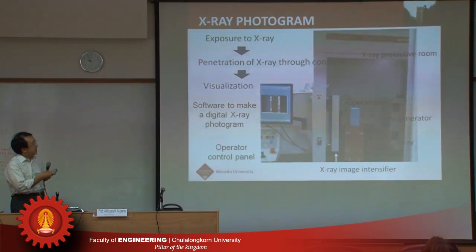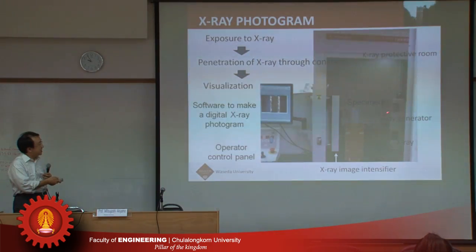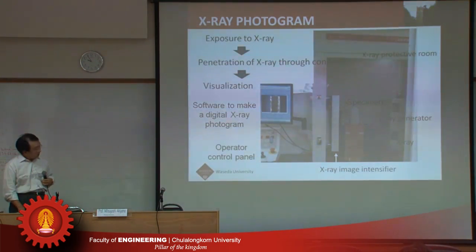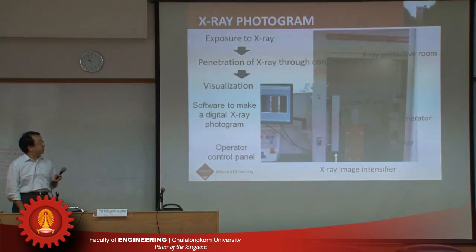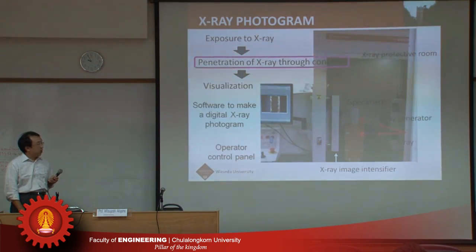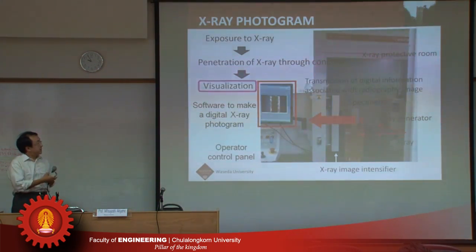The specimen can be rotated like this to take X-ray with different viewing angles. In the experiment, first, the concrete specimen is exposed to X-ray. Then X-ray penetrates through the concrete specimen. By using software to make an X-ray photogram, the rebars in the concrete specimen can be visualized.